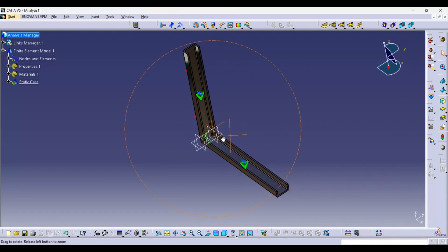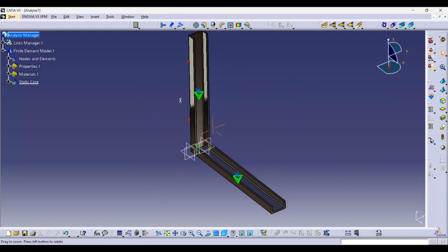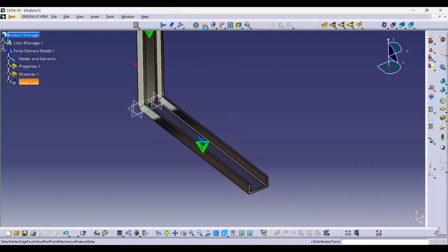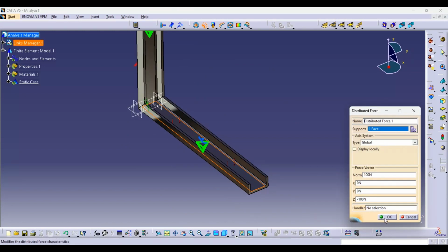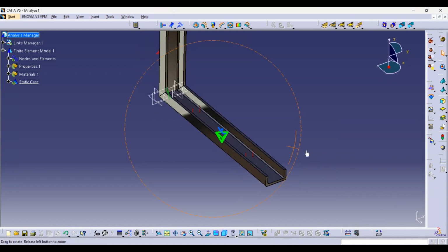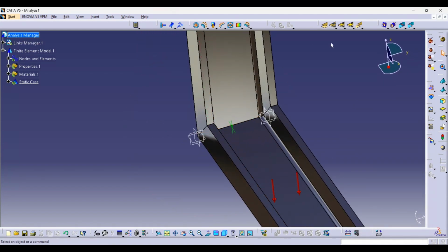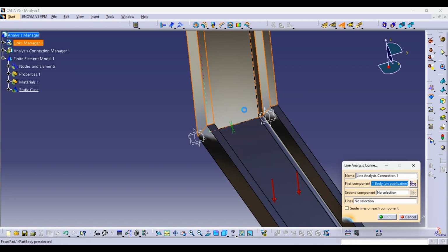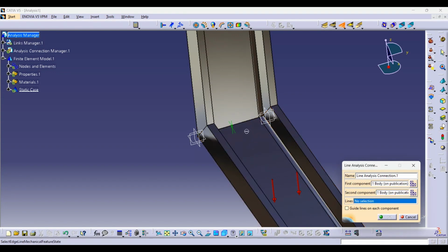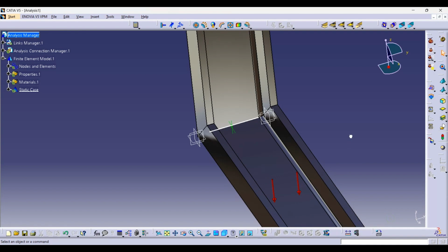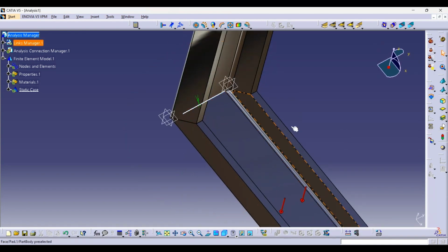holder. And this jig holder is then attached, for example, on a wall, and the force acting on the surface is 100 Newton, and we need to do the connection simulation for these two components and select the lines here as our rigid body, and then continue for the remaining lines so that we can simulate both parts in tandem, in connection, and as one part.